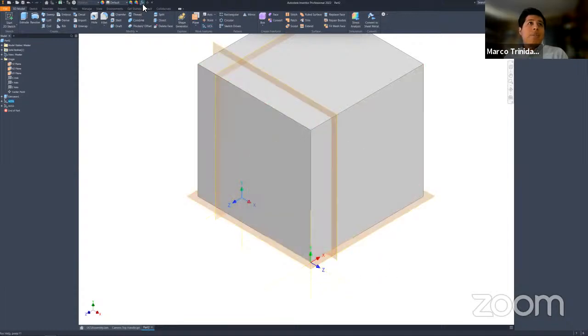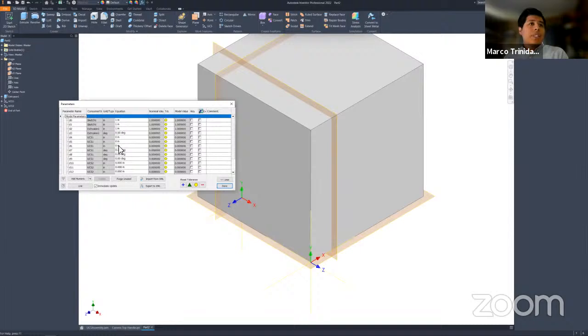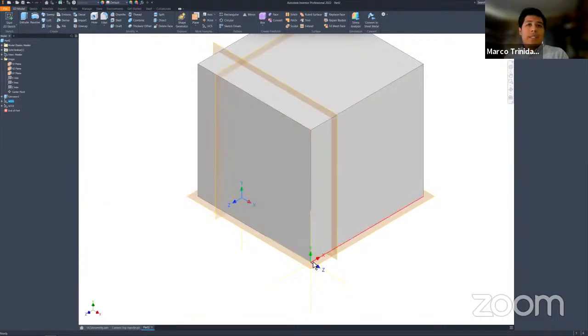And then you could go up to your parameters, and you could see once again that you have 3 additional parameters for that new point. And they are based off of that single point that you placed it on the cube. So when you set this one to 0, 0, 0, it goes by default to the origin because it was placed off into space. But this one, because it was placed on this point, its 0, 0, 0 is this corner of the cube.